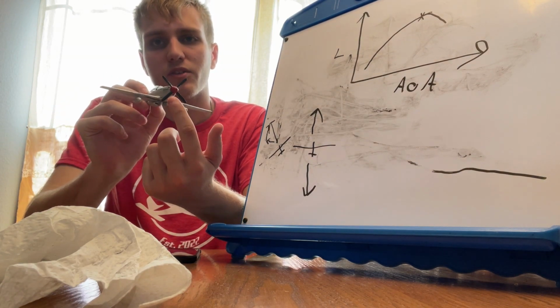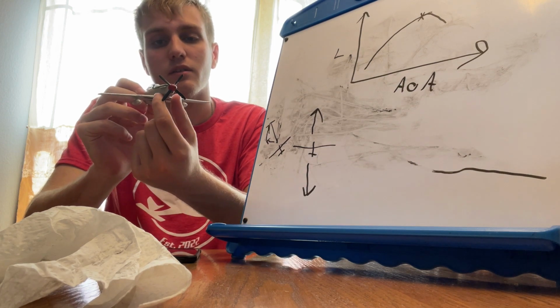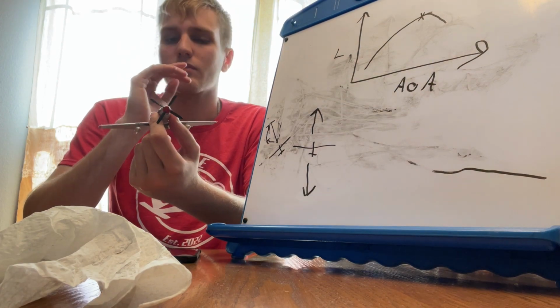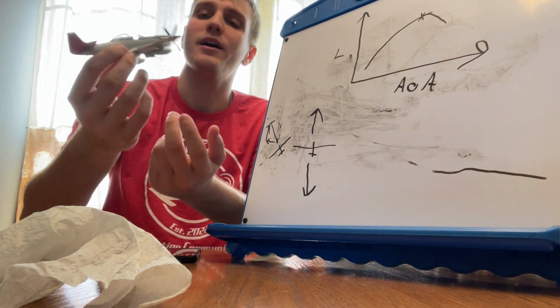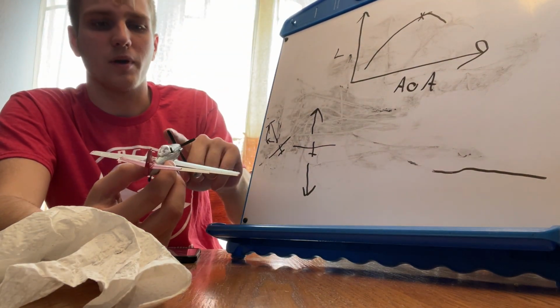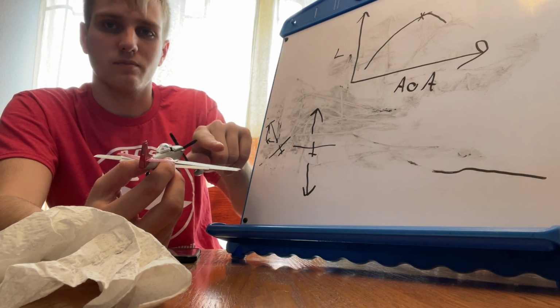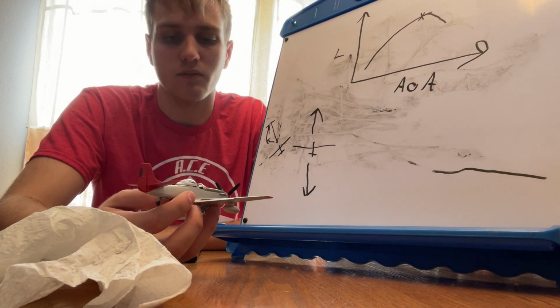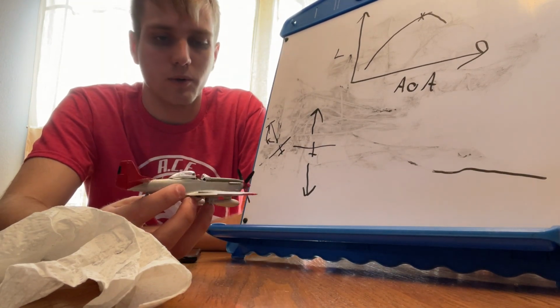So as the propeller spins, it's pushing against the airplane. I'm trying to figure out what angle you guys are looking at. The propeller is going to spin this way, and that's going to twist the airplane to the left. This is where we get some of our left turning tendencies. We have 4 of them, which I'll go over.